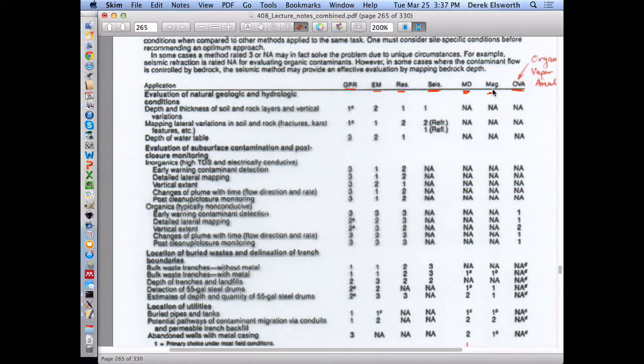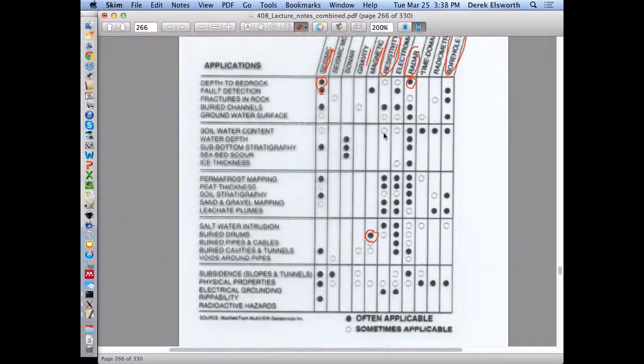And so the idea is boreholes, very limited, very accurate, because you know what you see is what you get. And therefore you're quite sure about what's there, but they are only a speck in your whole site. And to be able to fill in between those different locations, what you can use is some form of geophysics. It comes in a variety of different packages, all using a proxy for some feature of different rock types to be able to identify those different rock types or the plume. And so they have some measure of uncertainty attached to them, but if they're benchmarked against some direct investigation, then you have some reasonable confidence in what's going on.